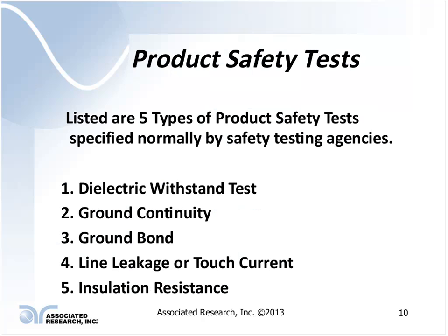You're troubleshooting a product that has a fault condition, and it doesn't always act the way it's supposed to. You go in there and start probing around, and sometimes you can make a mistake and end up getting shocked, even though you think you have everything shorted out. If there's an open circuit in there, you may not have a complete discharge path. But just a word to the wise if you're going through and troubleshooting circuits. Okay.